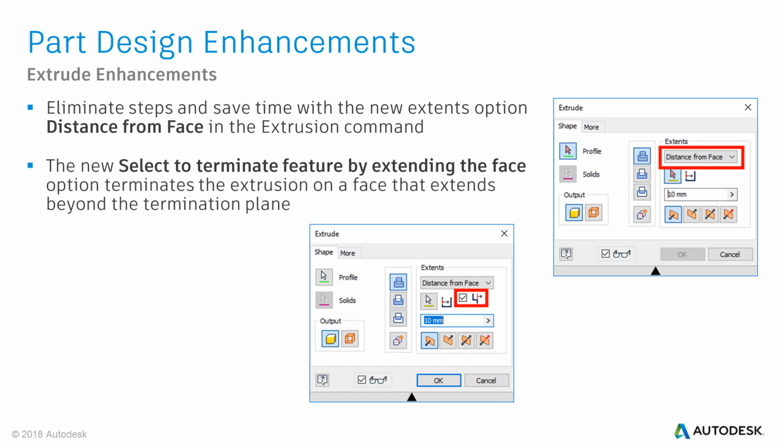Another personal highlight of mine, maybe for you as well. In the past, you couldn't have a sketch profile located on, e.g., an origin plane, while the intended extrusion should start, for example, 20 mm beyond the sketch profile and end another 50 mm from its start. To achieve that requirement, you needed multiple additional work planes. With the new distance from face option, you only need to select A, the sketch profile, and B, the surface or work plane where the extrusion should start from.